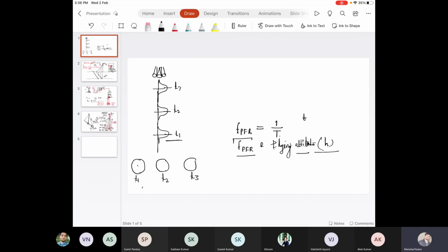So in like starting days when this technology evolved, the sensors which were there in the market, they had a limitation of a single pulse. We'll call it single pulse limitation. So single pulse limitation tells that this transmitter doesn't fire the beam T2 until it receives the return of T1.